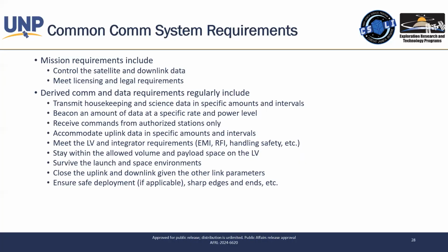The other thing you need to consider is what kind of data rate do you need? How much data am I generating aboard my satellite? And how often do I need to contact it and offload that data? That's going to be a big design decision: this is a transceiver board that can transmit 5 kilobits per second versus megabits per second, right?